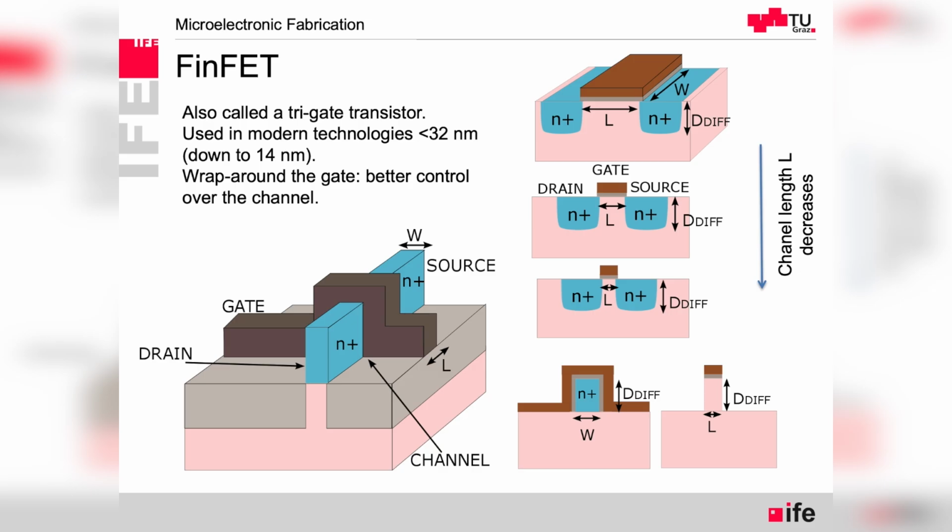This kind of transistor can be done in the substrate, but it can also be done as silicon on insulator, where at the bottom side we also have insulator, or as a nanowire, which can be controlled on all sides. Very often we call them tri-gate transistors, because in some technologies at the start they would be made in batches of 3 fins.